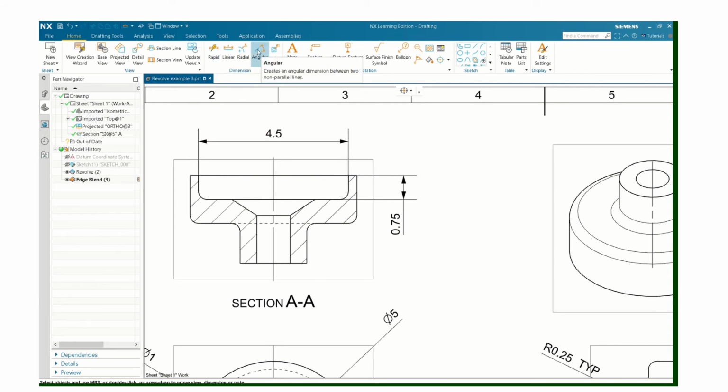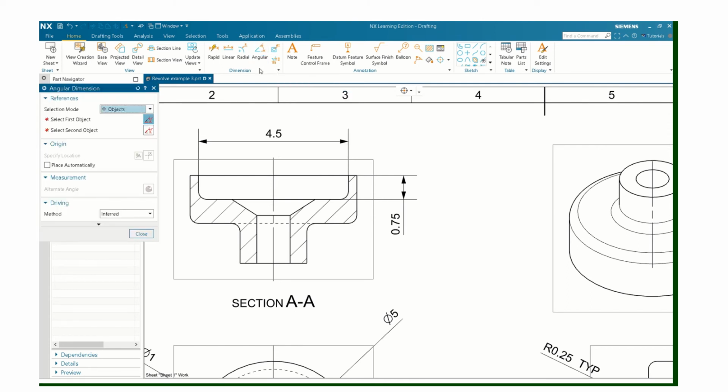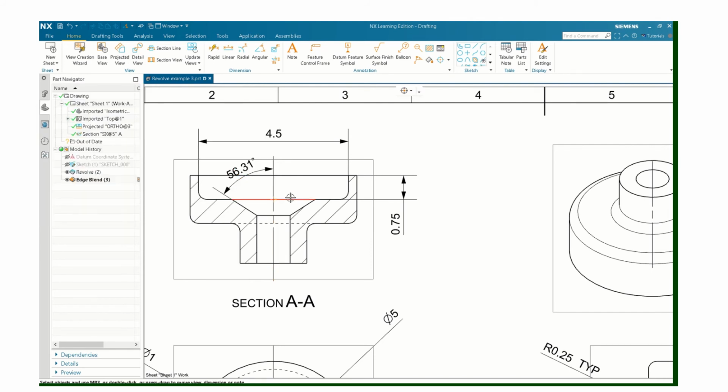Now, if that angular thing isn't showing up, you can turn it on, the angular, just by putting a check mark next to it. So maybe what we can do is do it off of this center line here. Now, that's just a function of those diameters. And I guess the reality is I don't have to have that on there because you can develop it from the diameters and everything else. But I think I'm going to leave it on there for good information.